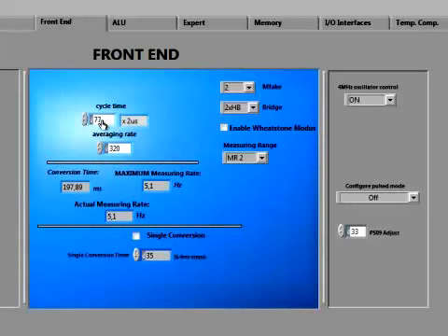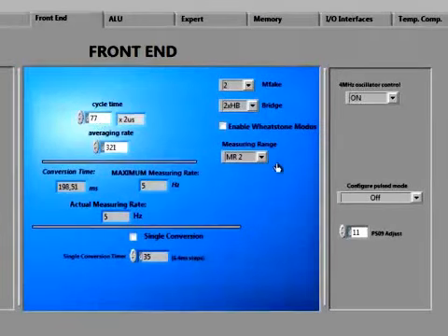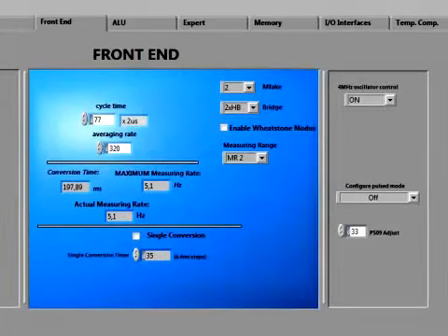The charging constitutes about 30% of the cycle time and must be long enough to allow the load capacitor to charge completely. If the cycle time is too small, there occurs an overflow that is indicated on the measurement sheet. You can set the cycle time in multiples of 2 microseconds or 100 microseconds. For continuous measurement mode, it is set in multiples of 2 microseconds.